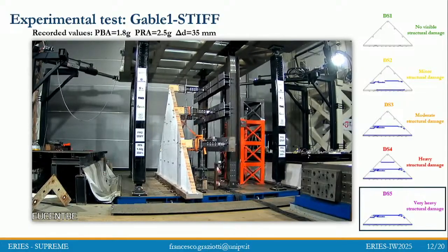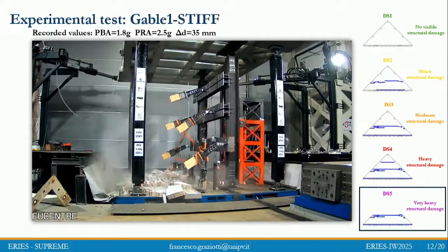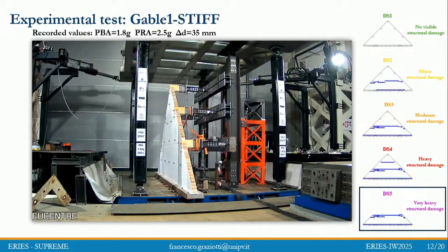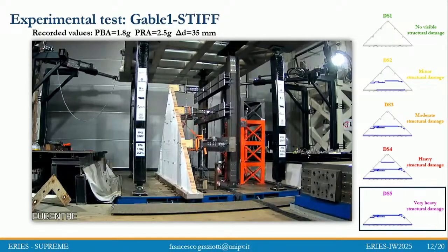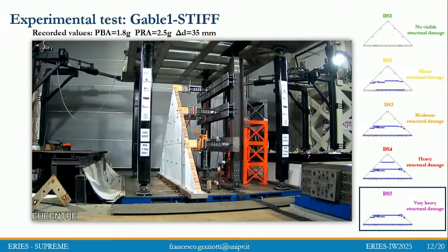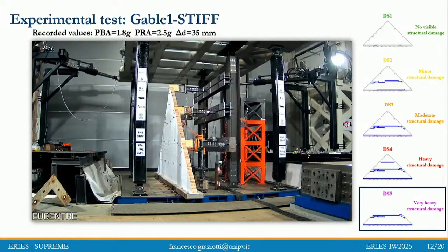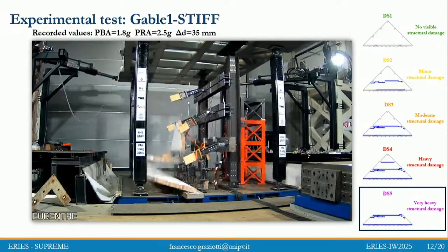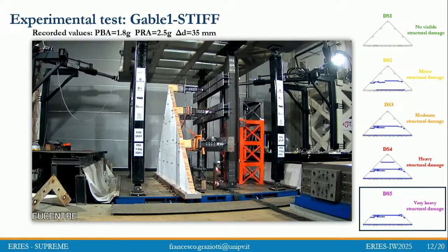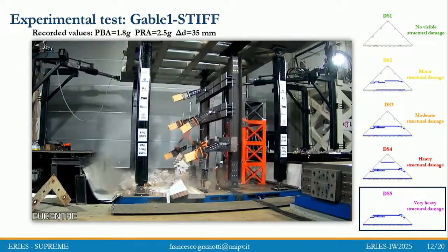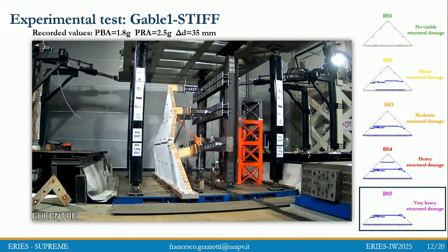This is a video of the first test, the one that had nominally exactly the same acceleration top and bottom. You may see there is some small out of phase between the two tables, but this is nominally the one with the same acceleration top and bottom. As you can read on top of the video, we reached a pretty high acceleration of almost 2g at the base.